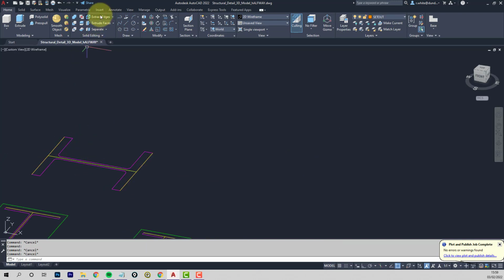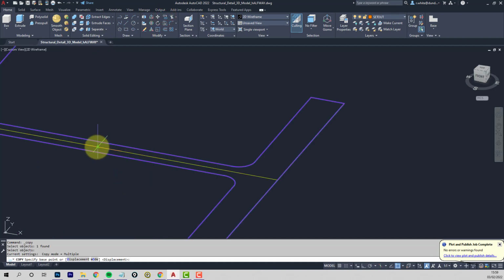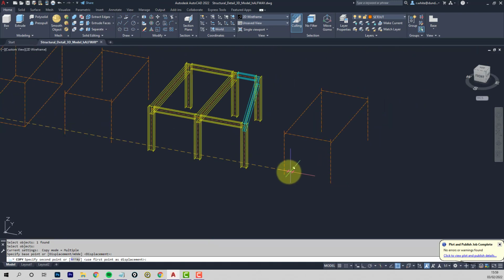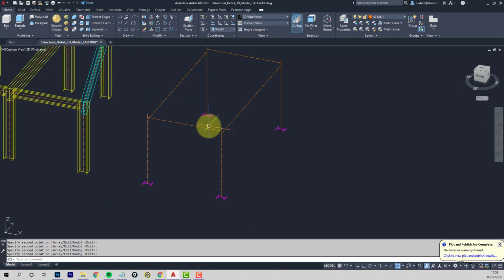So I'm going to copy, pick the column shape, enter, use the middle of that line, and we can drop 4 of these on. So I've got endpoint, endpoint, end, and end. Okay, and this is where these commands start to come in now, using the solids.